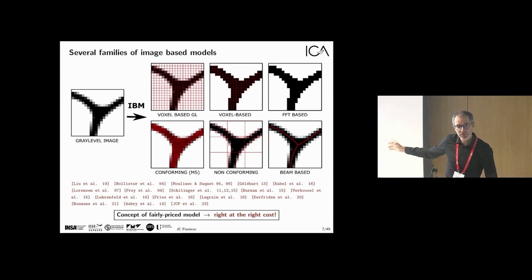And another way of building models, that I will talk about after, is in computational mechanics. We also have simplified theories like beam models. Beam models consist only of a line, and the cross-section is interpreted as line mechanical properties. And I will show how to build this kind of model, which is very cheap because there is a very small number of degrees of freedom.